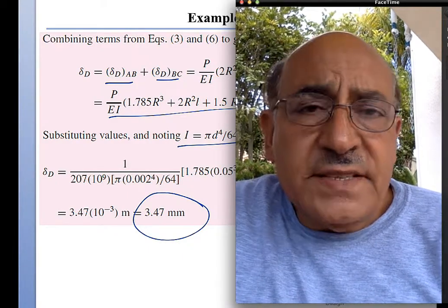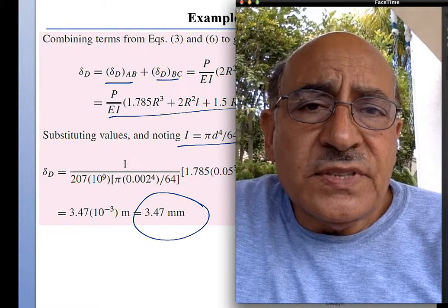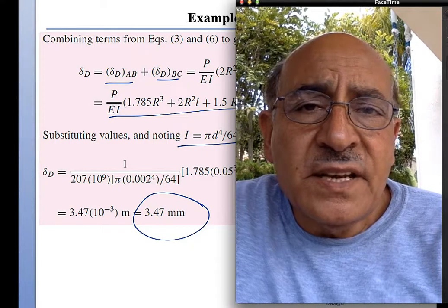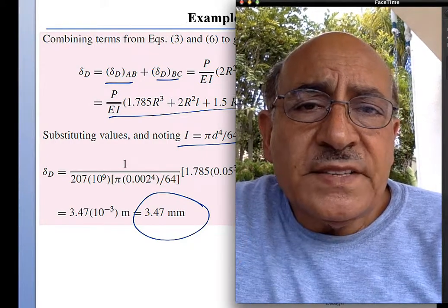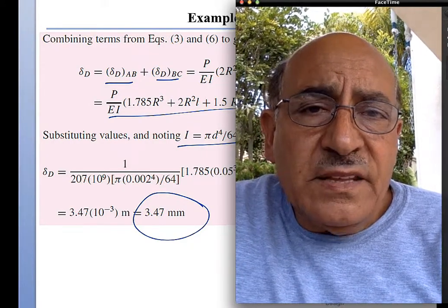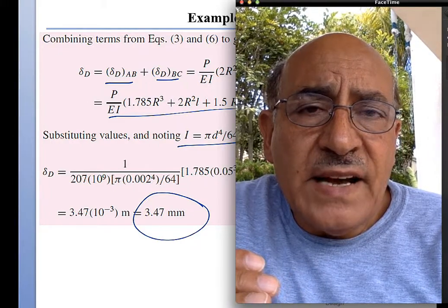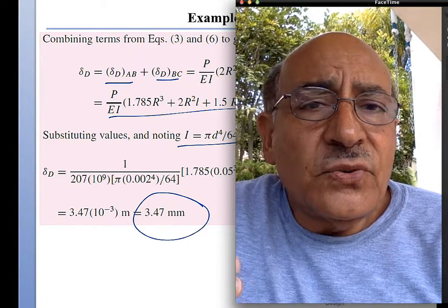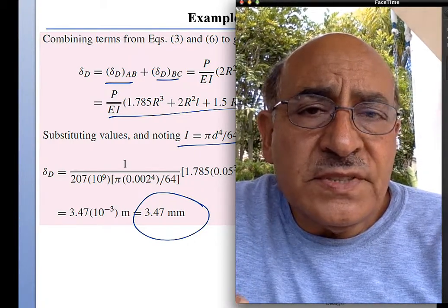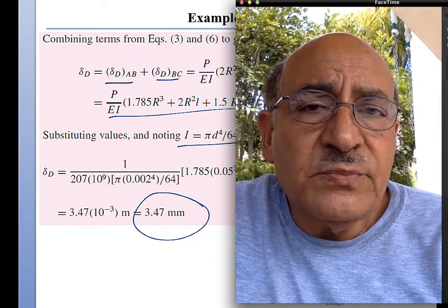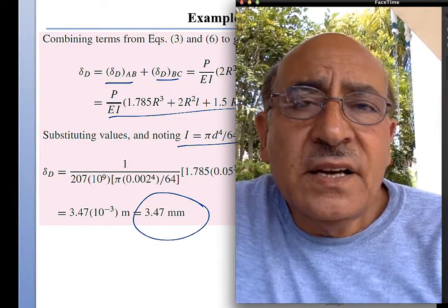And the easiest way really is to use the deflection or the rotation idea, because in a lot of cases we know at specific points in the beam either the rotation, if the beam sticks out of the wall straight out, so the rotation is 0, or maybe if it is attached to the wall with some kind of spring that has a stiffness, rotational stiffness, then we can compute the rotation from that side.